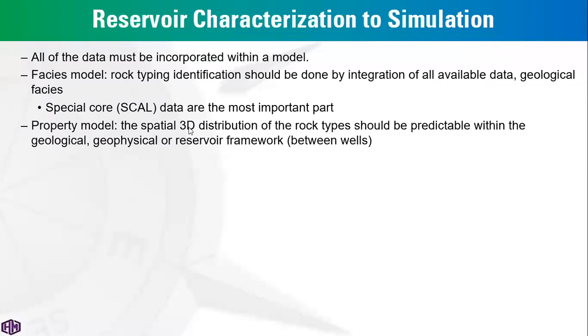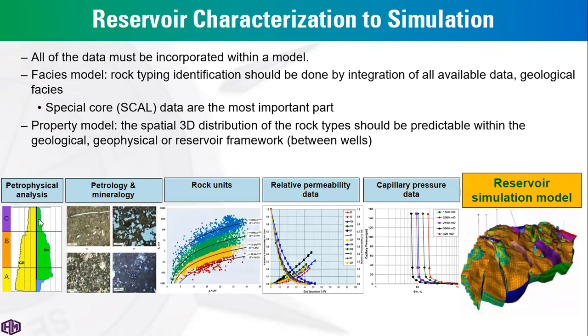So reservoir characterization is a critical process in such reservoir management or reservoir simulation. So all of this data is important: petrophysical analysis of well logs, petrology or mineralogy, rock units from core data, relative permeability data, and capillary pressure data. All of this data must be defined to start the dynamic modeling phase to get a specific 3D simulation model.